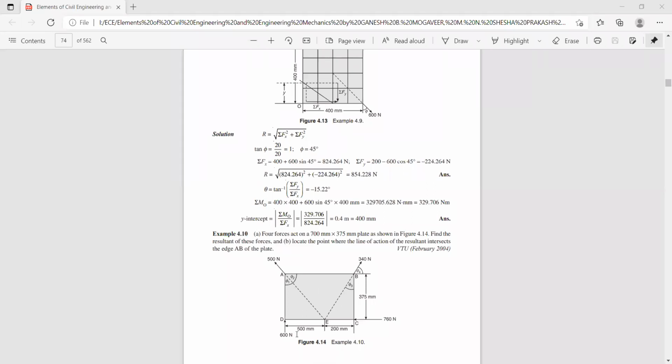Similarly, you can find this angle, correct? Tan theta 1 is 500 divided by 375. You'll get this angle with respect to the y-axis. So 90 minus that will be the remaining angle with respect to the x-axis. Now just find the values of theta 1 and theta 2. Take a piece of paper and a calculator and find these angles, theta 1 and theta 2. Could you do this?